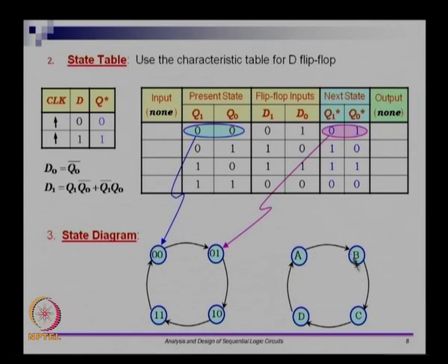So, in fact, this is just the state diagram of the up counter that we had. We just designed that in the last class, right. So, if I go and read the flip flops and directly give them as output, then this is actually the state diagram for an up counter. So, up counter should go from 0 0 to 0 1 to 1 0 to 1 1 back to 0 0. So, this is a picture for an up counter.